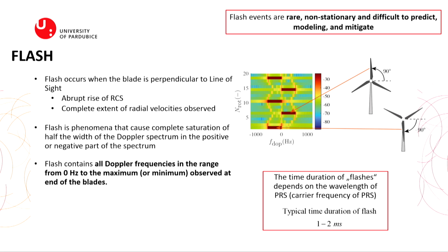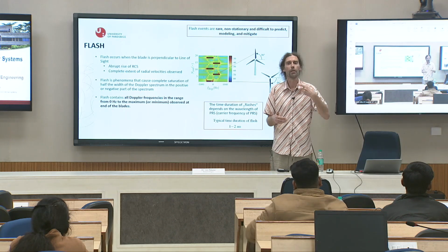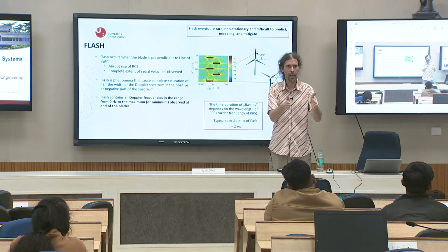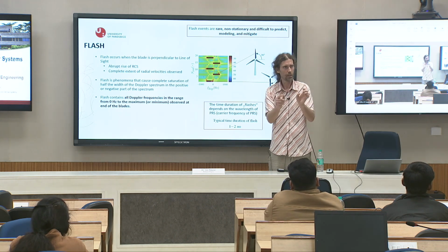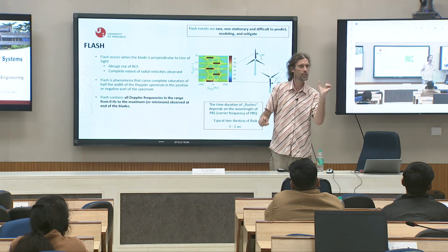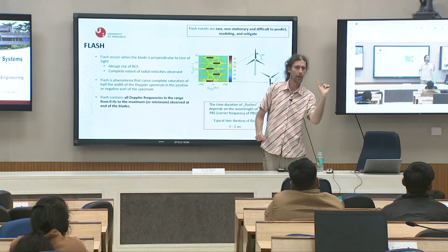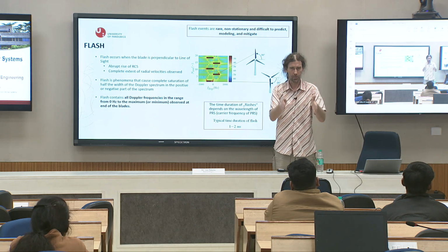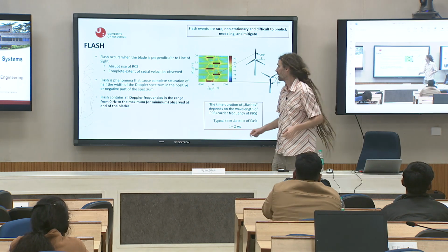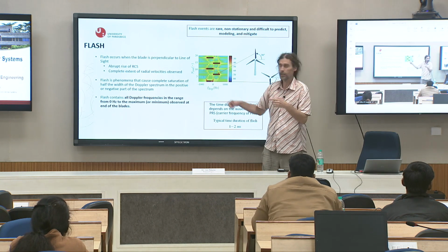As an example, if my voice has a maximum frequency of 20 kilohertz, or a bandwidth of 20 kilohertz, how do you need to sample? Double, 40 kilohertz. And if I undersample, aliasing occurs. All these higher frequencies will be mapped into my base frequency, and it is completely the same.